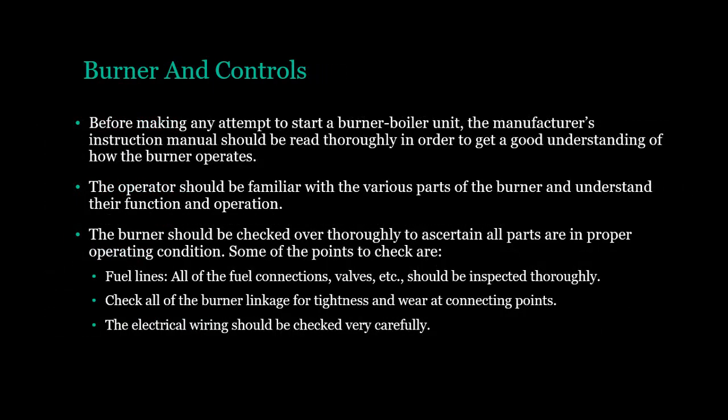Before making any attempt to start a burner boiler unit, the manufacturer's instruction manual should be read thoroughly in order to get a good understanding of how the burner operates. The operator should be familiar with the various parts of the burner and understand their function and operation. The burner should be checked over thoroughly to ascertain all parts are in proper operating condition.